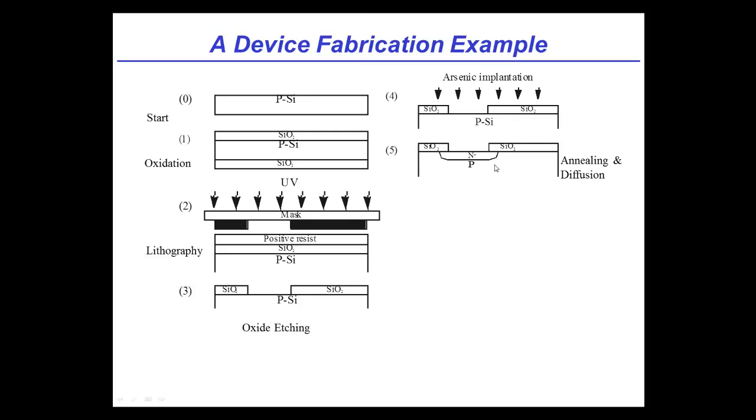That's clever. So basically the silicon dioxide is used essentially as a window or a stencil for how you dope it. That's cool. Right, that's right. So what we've done now is essentially create a localized N-type region in a P-type wafer. And now, maybe, Michelle, you can talk about the next step, which is putting down the metal.